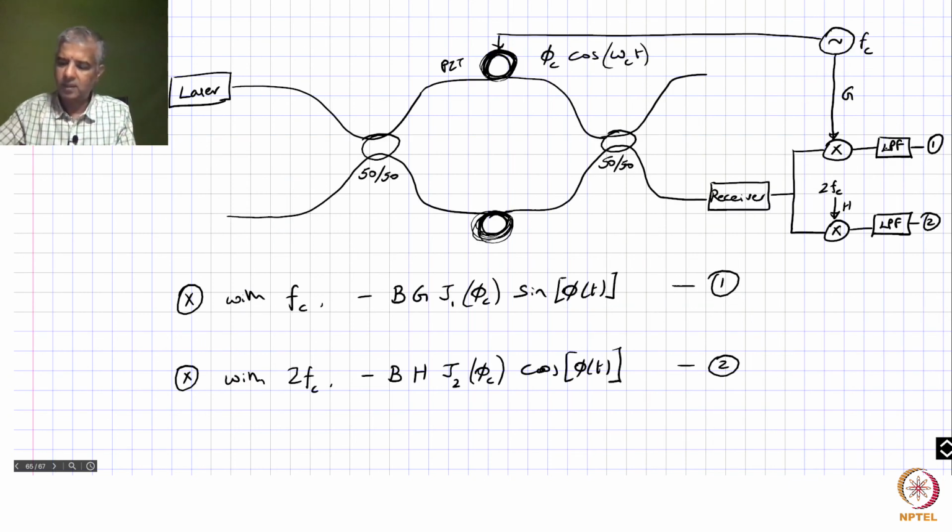That is something that I did not explicitly mention previously. When you do this beating, you also need to incorporate this low pass filter before you extract this 1 and 2. So, by low pass filtering to essentially include the essential components, like if you are trying to pick up something at 100 hertz, then you do a low pass filter around that, so that you are not actually accumulating a lot of noise from higher frequencies. Okay. So, you need to use this low pass filtering judiciously.